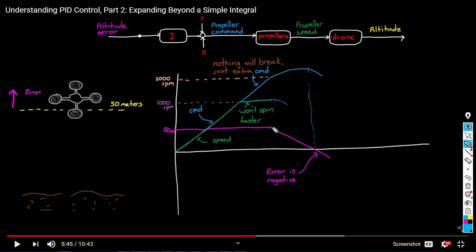I need to calm down my speed, because now I'm at 1000 RPM. In here I want it to start to decrease. My command signal should decrease from this point rather than going up this way and then decreasing. So that's the windup. Ideally, when you do anti-windup, we let it go this way rather than this way, so we see the saturation.